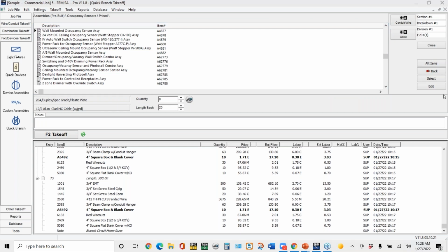And can the adjustment for room height be done as an adjustment at the takeoff level? Yeah, if you're normally using 15 to 20 feet and you've got high ceilings, bump it up accordingly. Add another 5 to 10 feet if it's a 20-foot ceiling or something like that. But again, you'd have to manually add that. If you've got 10 receptacles, instead of putting in 200 feet, you might put in 300 feet or 350 feet to adjust it.